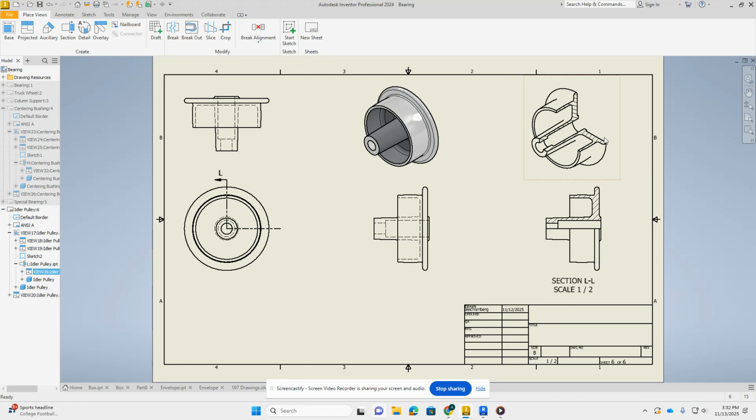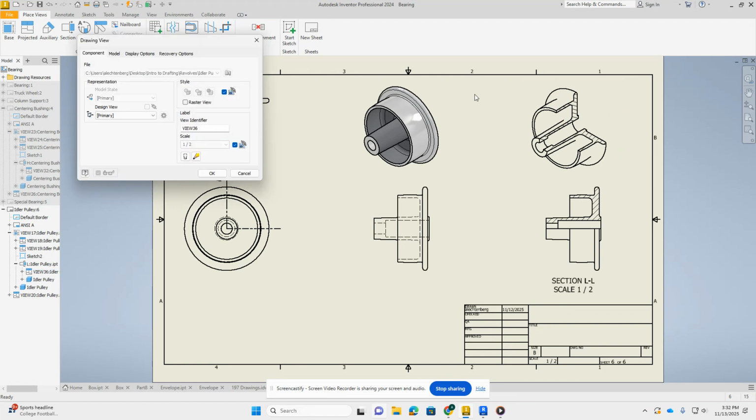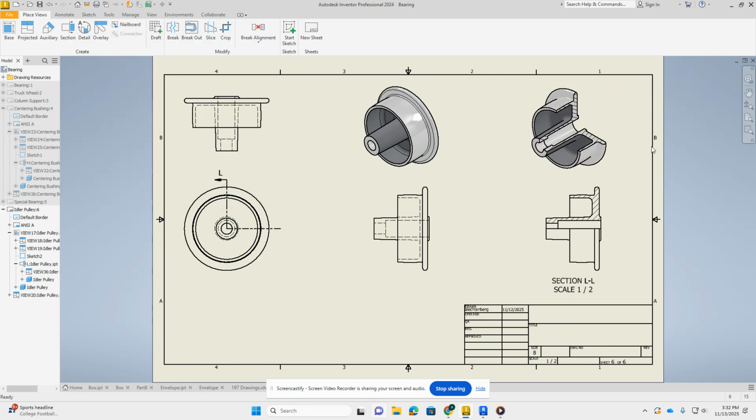I'm going to move it over here and I'm going to double click on it. To color it, it is a different step, process, whatever, but basically all you're going to do is just uncheck this and then you can color it and hit OK. Colors it. We're going to go over here to detail now and we're going to do the zoomed in section of the drawing.